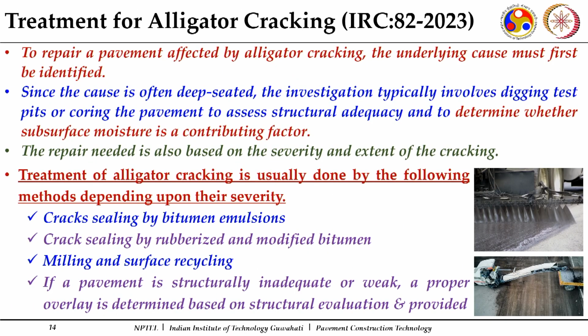Now, as I mentioned, there are so many causes. So, it is very important to know whether it is inadequate thickness of the pavement which is creating a problem, or the presence of moisture in the underlying layers, or specifically stripping of the underlying bituminous courses which has happened. Then the treatment has to be planned so that it can survive for a good period of time. Since the cause is often deep seated, the investigation usually requires